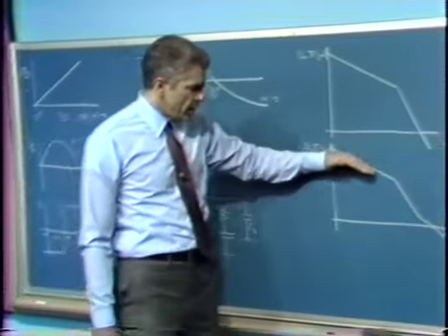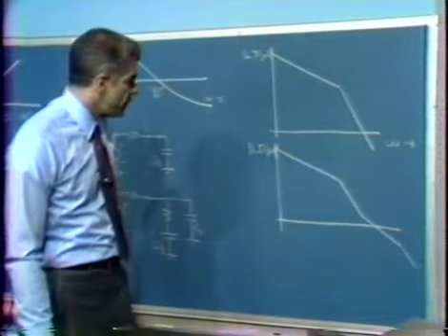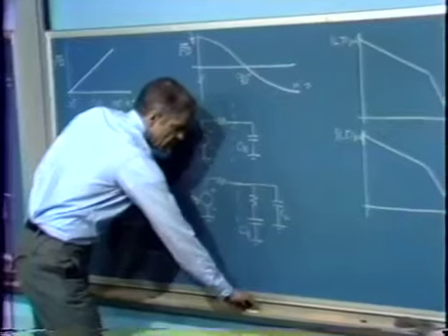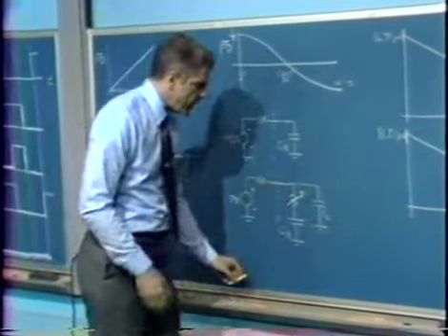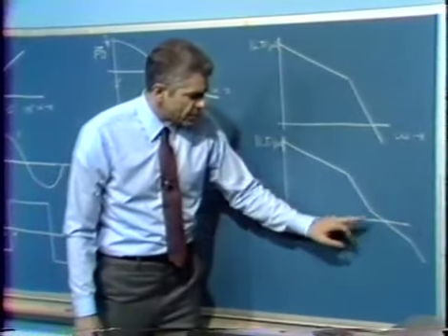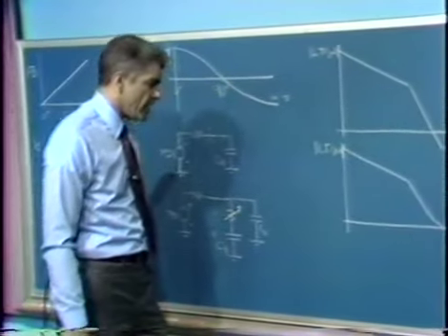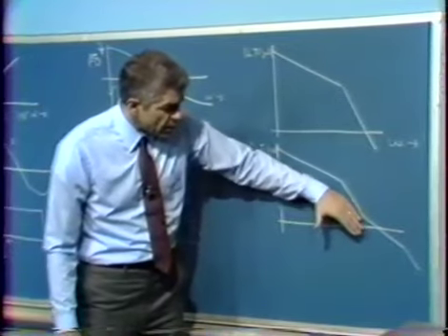This is the way we've arranged a demonstration system using the 565. In fact, what we're able to do in the demonstration system is change this resistor. The net effect of doing that is principally to change the location of this zero, so we can get a family of responses from our phase locked loop, or a family of loop transmissions